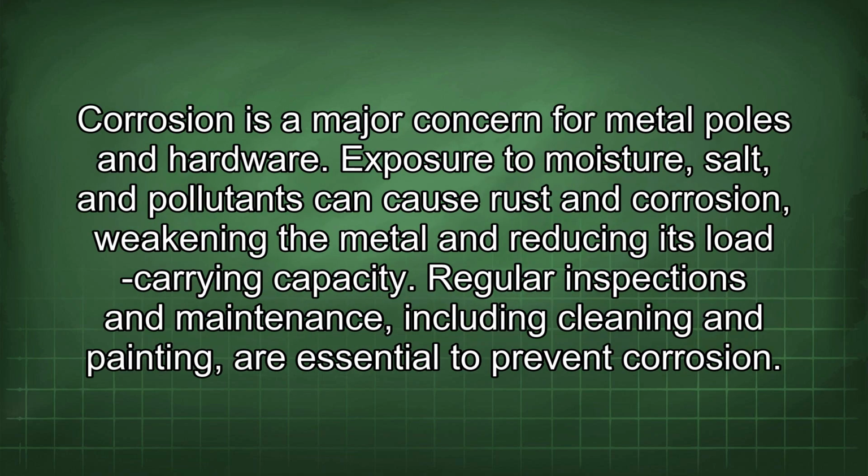Corrosion is a major concern for metal poles and hardware. Exposure to moisture, salt, and pollutants can cause rust and corrosion, weakening the metal and reducing its load-carrying capacity. Regular inspections and maintenance, including cleaning and painting, are essential to prevent corrosion.